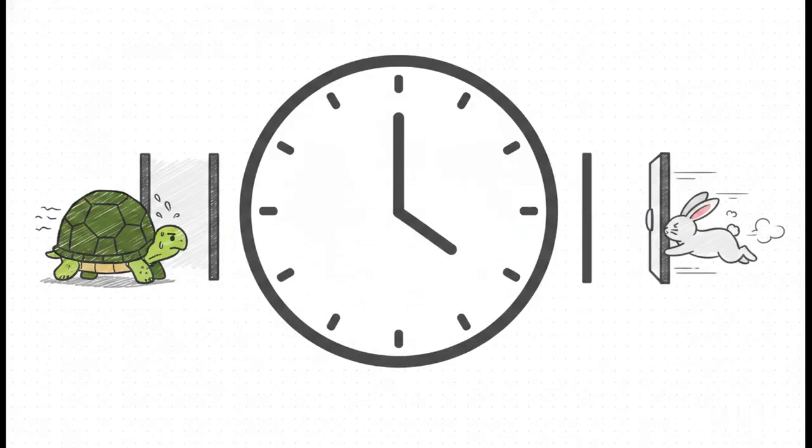Now, what's really interesting here is that a circuit can be logically flawless but still fail completely due to physical timing. Enter static timing analysis, or STA. STA is a technique that meticulously checks for critical violations. For instance, if a signal traverses its microscopic highway too slowly, like a turtle, and arrives after the clock edge is fired, that is a setup violation. Conversely, if a signal races through too fast, like a rabbit, slipping away before the clock edge can properly capture it, that's a hold violation. Analyzing and fixing these thousands of timing paths is the ultimate puzzle for VLSI engineers.